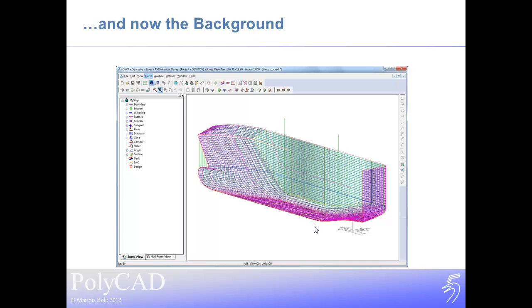So there are some particular strategies that can be used to develop a fair set of curves. That said, all of the processes have to be invoked manually. It is possible to put all this into a macro, but it's not possible to run the macro at the call of the mouse, as in we move one point and get the macro to run directly, interactively. So in this respect, what I've attempted to do is take the idea behind Lines and develop an automated process that can achieve that.